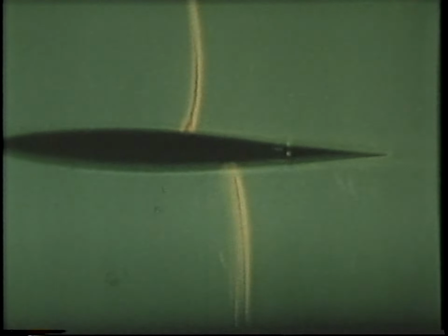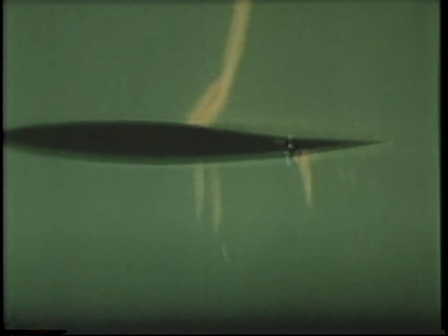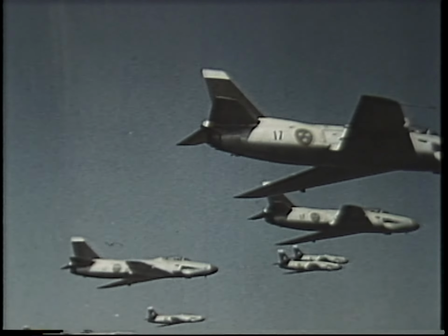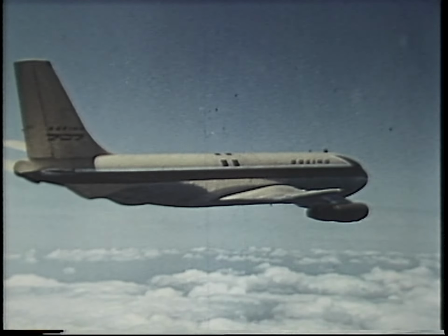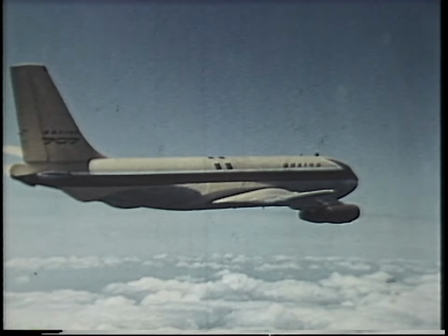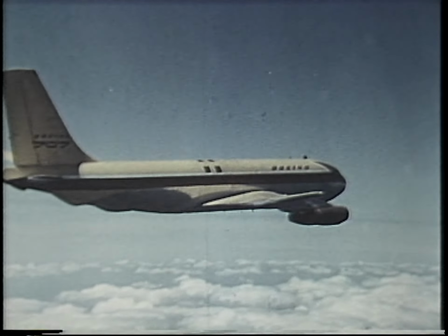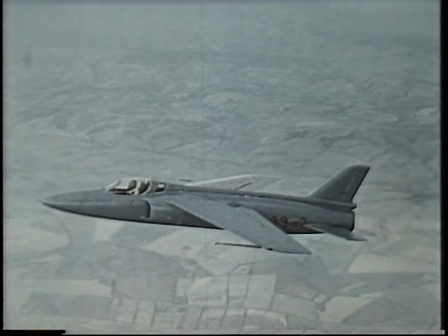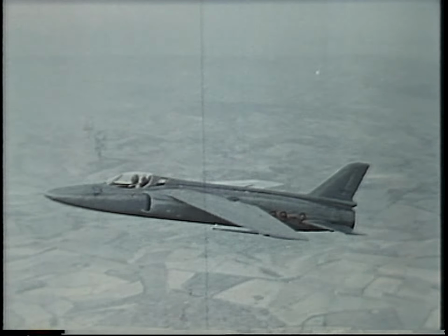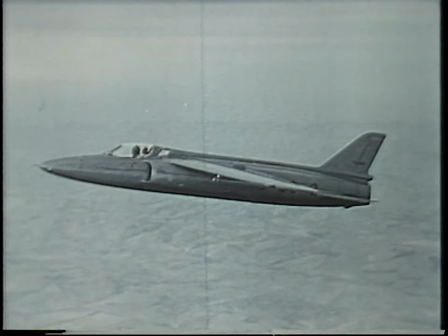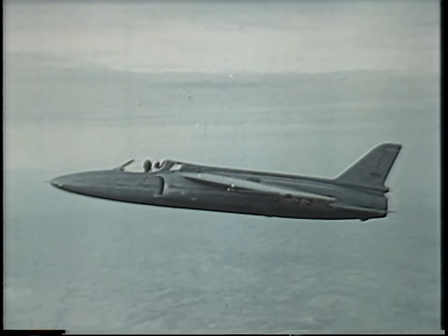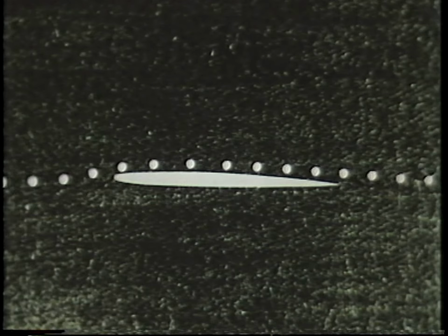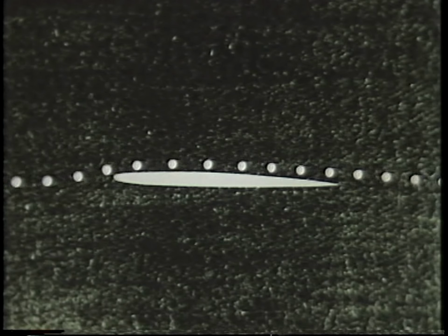How have aircraft designers overcome these shock wave troubles? One way is to put them off to still higher speeds by actually raising the critical Mach number of an aircraft. The designer does this in two ways. First, by using relatively thin wings, wing sections whose thickness is small compared with their width from front to rear. The thinner the wing, the less the air is speeded up while traveling over it, and so the higher the critical Mach number.